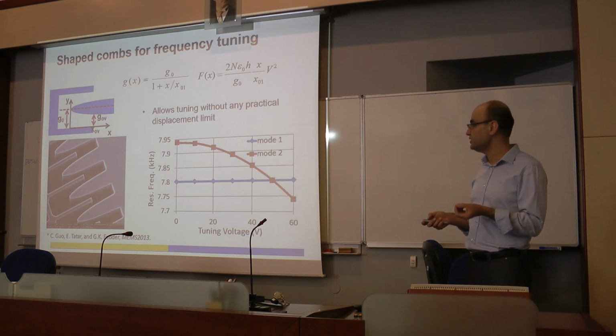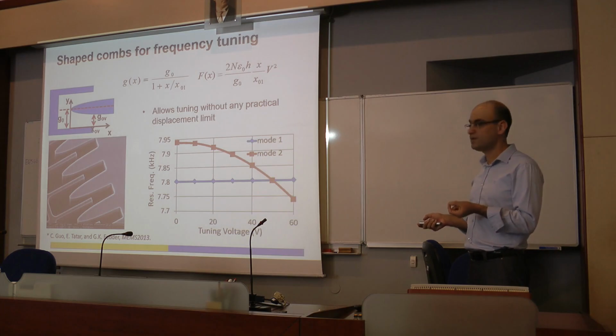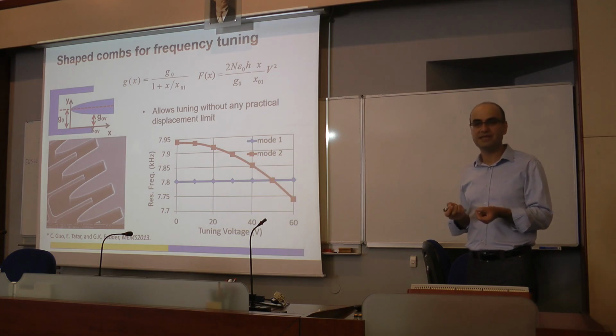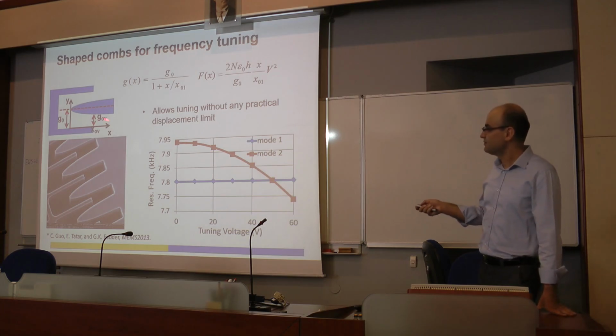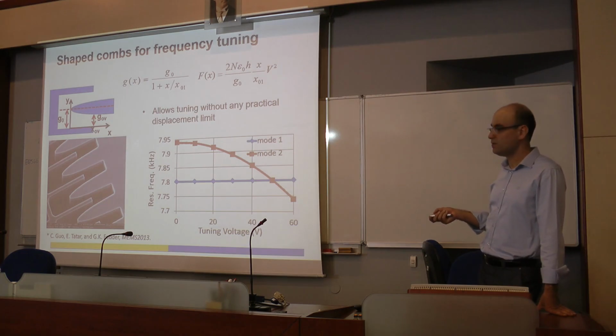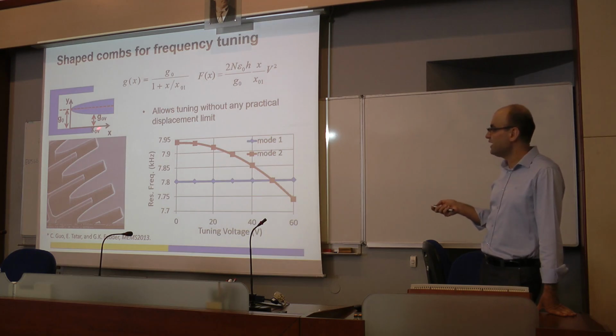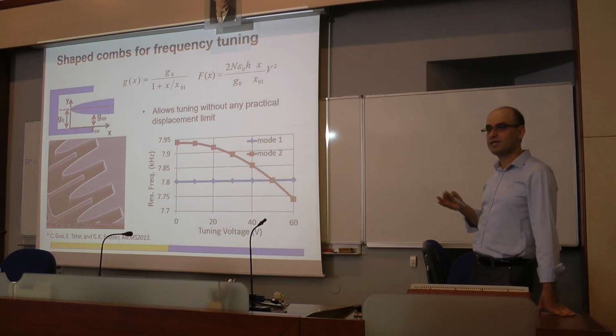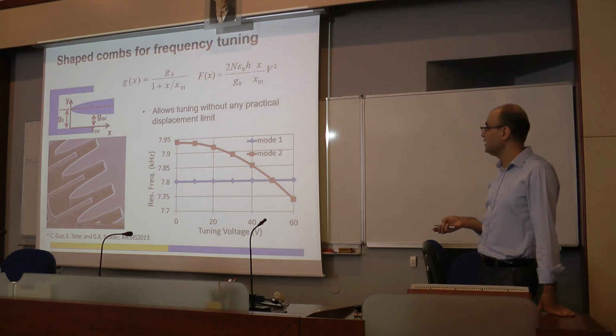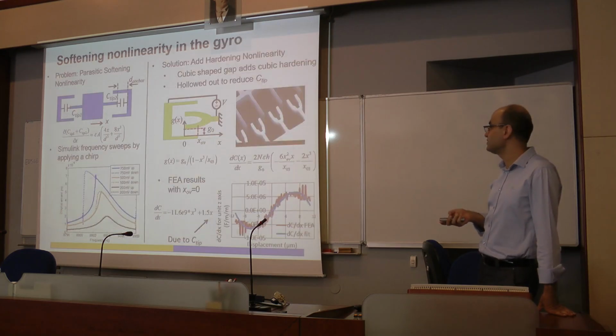What is the advantage here? Normally you use parallel plates, which are extremely nonlinear. This has no nonlinearity problem, or very, very low nonlinearity compared to parallel plates, and you can have very high displacements with no issue. And you can place these on both drive and sense modes.